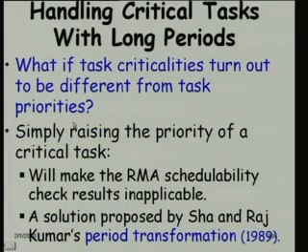So, for taking care of both self suspension, single or 2 times, and context switches, we can do it very easily. But now, let us see another issue in using the rate monotonic algorithm in actual system development.